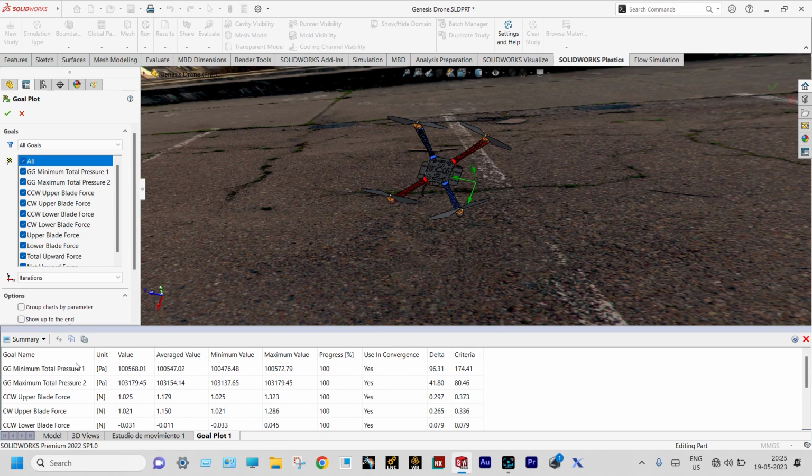So in this case, the angular velocity is actually more. It is 4000 RPM. And again, our main criterion should be to see the net thrust or net force. We can see here the net thrust is positive. It is 0.699 Newton. It is very less, but it is sufficient to move the drone in the upward direction. But if it is more, then it will be better. So we need to run the propeller with more than 4000 RPM, right? Let us close this one.